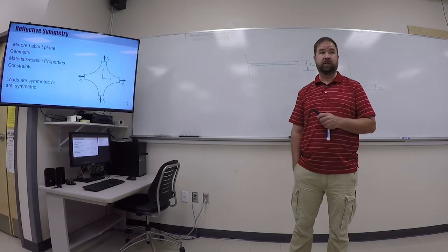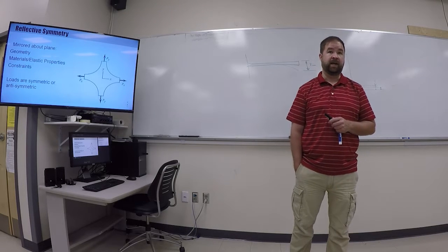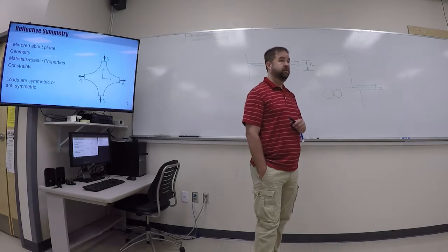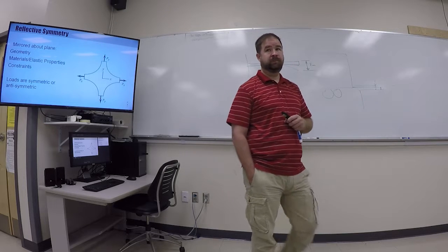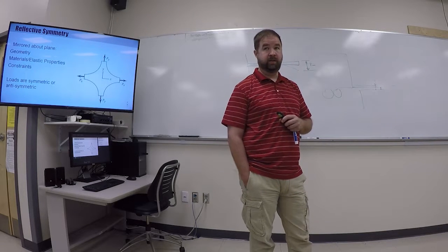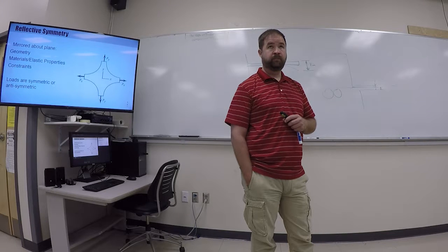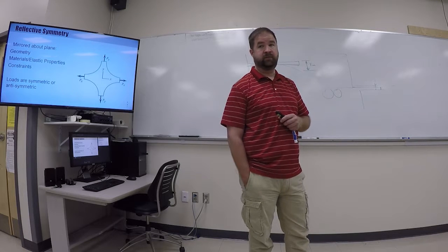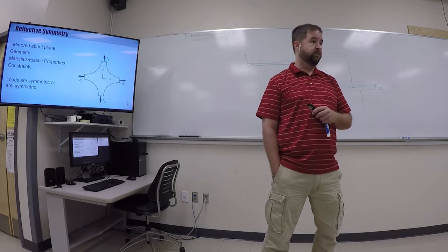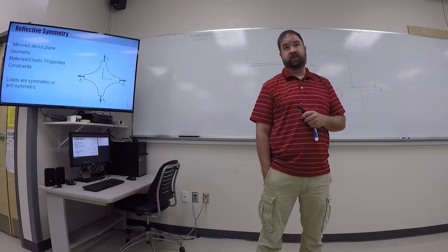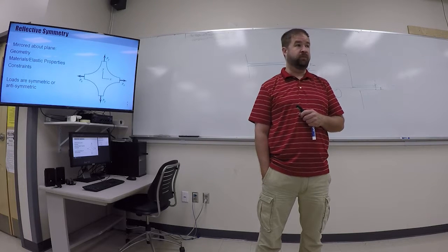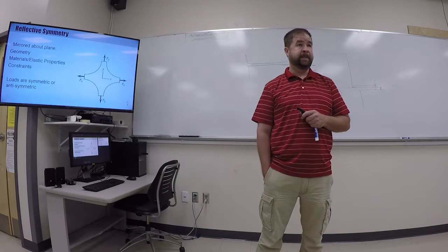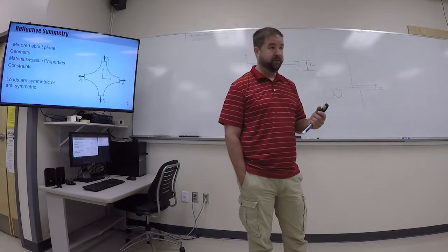So airplanes are typically symmetric. I could take advantage of symmetry to model half of the airplane to really simplify the amount of material that I need to do. And that works as long as everything is truly symmetric and as long as the airplane is sitting, let's say, on the runway, then all 3 wheels are touching the runway and everything would be completely symmetric.